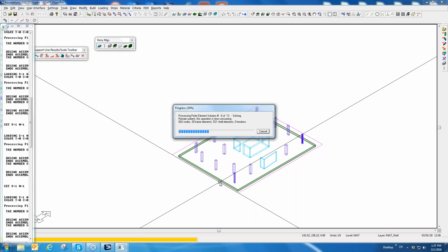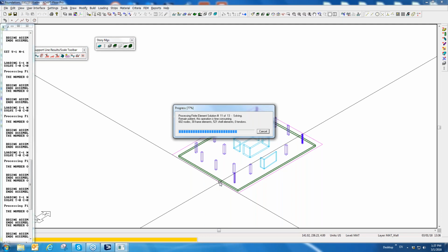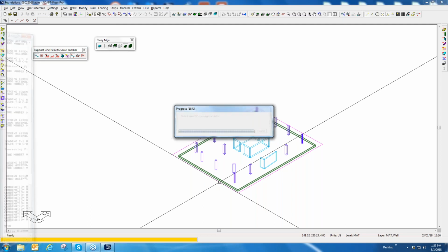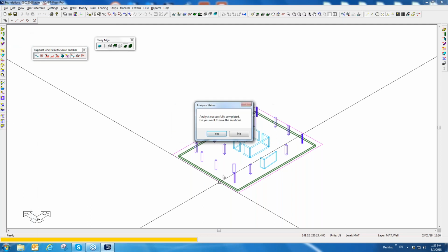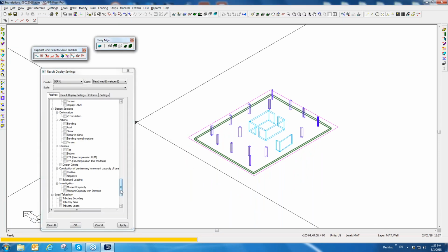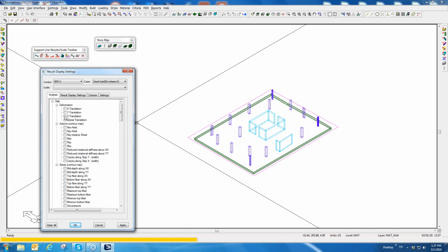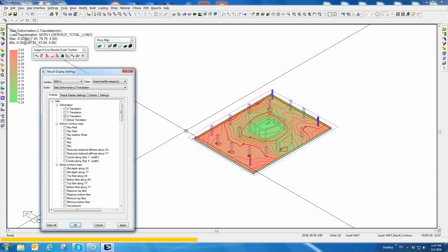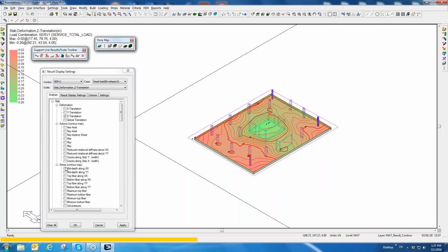This will allow us to obtain a solution now considering the effects of both gravity and lateral load. So we'll go ahead and say OK. And if I just compare the service 1 deflection between this run and the previous run, actually let me compare the stress. I think this deflection is 0.26. The previous run was 0.23.